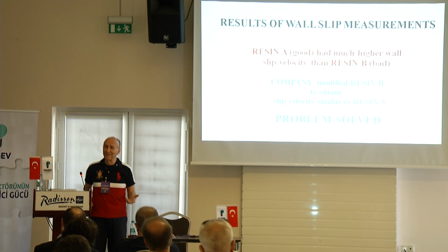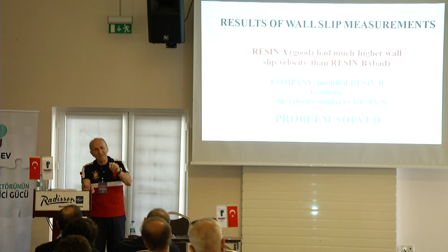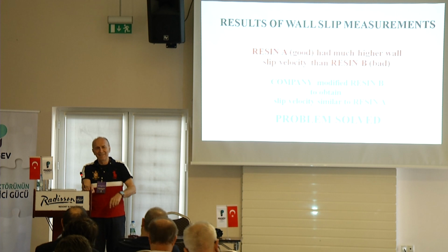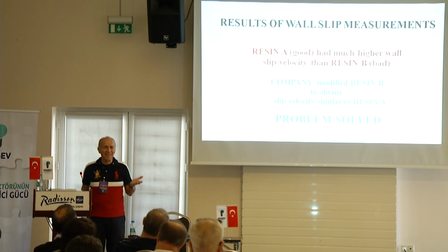And what do I see? Spelled out, black and white, this resin contains a slipping agent. So they added a slip agent in there. Okay, that was the problem.